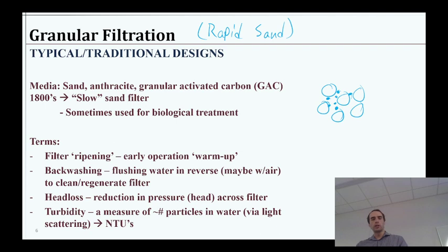Okay, so then there's backwashing. Obviously, we're going to flow water backwards through the granular filter, push all these particles out. We're not going to flow it so fast that we lose our granular media, sand grains, but they're pretty heavy, right? So we can use that sedimentation for the granules themselves, pushing all these smaller particles up, out, and away, and collect that and send it to wastewater for treatment.